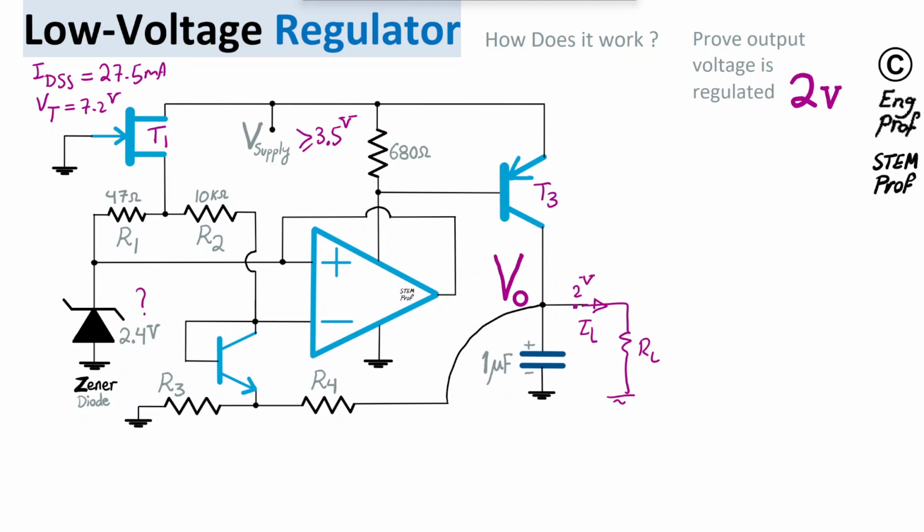We also have a low-current NPN Bipolar Junction Transistor T2 that provides the offset voltage in this circuit, which I'll talk about. The bias of the Zener diode happens via resistor R1. There is a specific reason this resistor is selected to be 47 ohms, while R2 will be a large resistor, 10 kilo ohms, as an example.